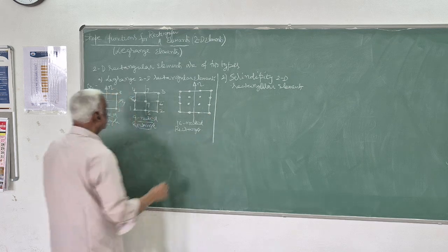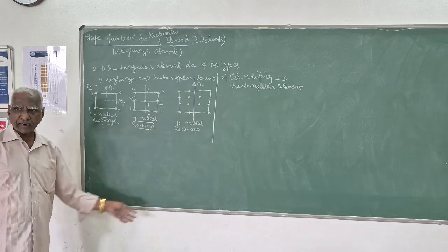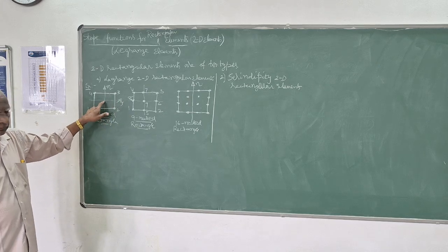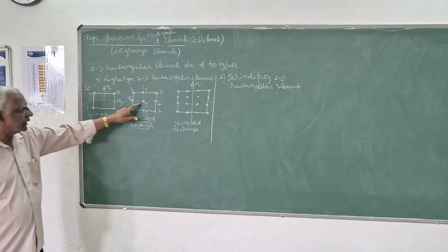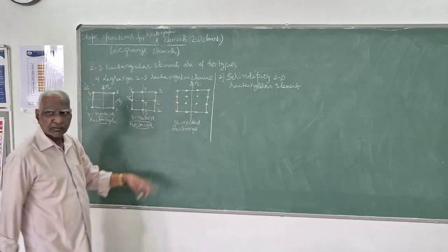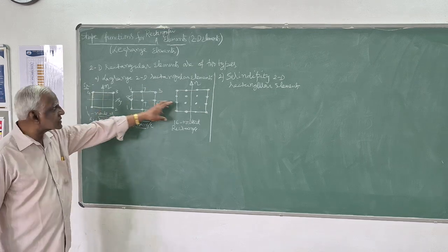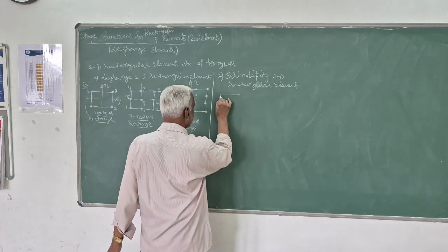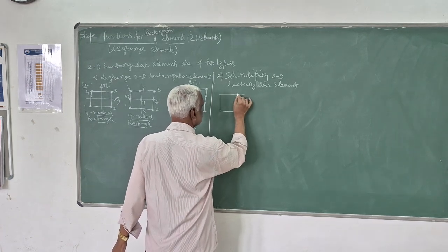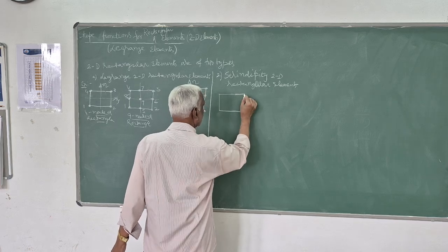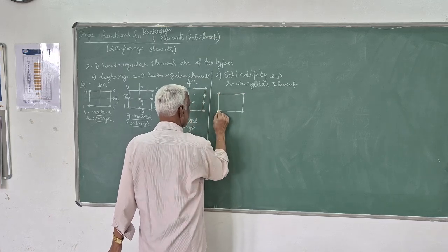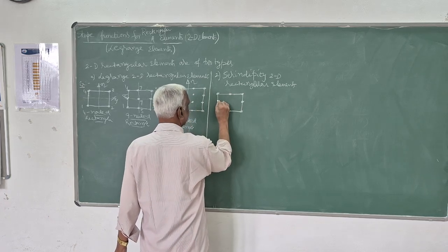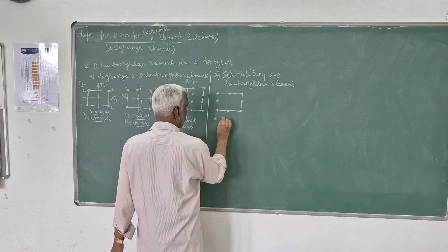These are all called Lagrange type of rectangle elements, wherein here no middle node, intermediate inside node, here you have one inside node, here you have 4 inside nodes. If these inner nodes are not there, then it is called a serendipity type of element. If the nodes are distributed only on the edges, then it is called a serendipity type of element.